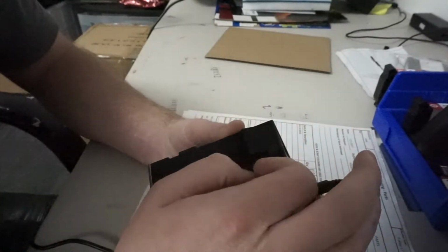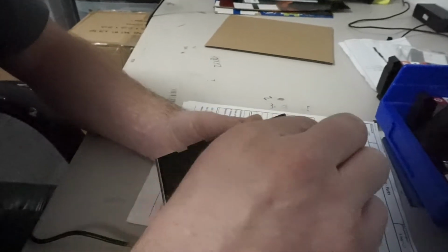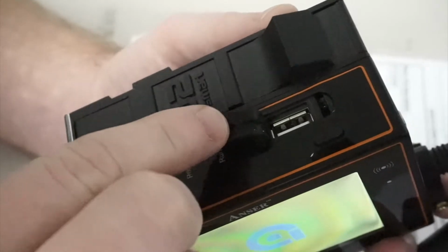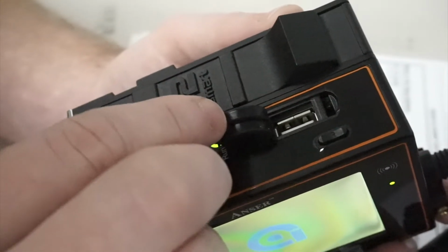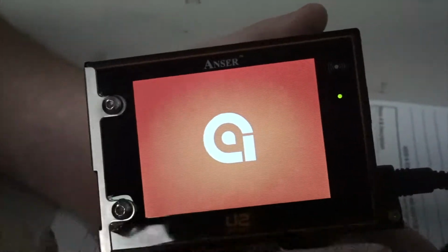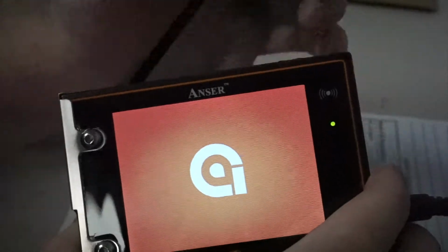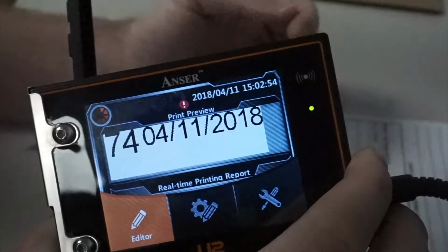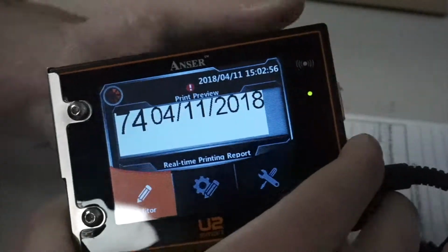You got your slot for your thumb drive here. You can create your messages, of course, in Message Pro, up to 999 of them, and transfer them to the printer. Please keep in mind, if you've already created messages on the printer itself, when you put in that thumb drive with those messages, it will wipe it unless you've already backed up the messages from the printer itself.